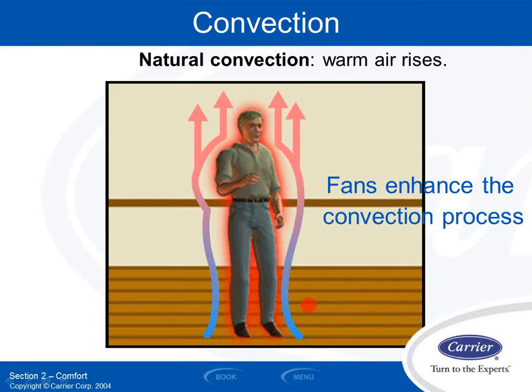all based on my body being the heat source. It's very similar for you guys that have been in apartment buildings or houses that have baseboard electric heat or baseboard hydronic heat sources. There are no fans in those baseboard heaters. Basically, the coil just gets heated up by the electric or water you're providing to it. When it heats up, that air rises out of the baseboard and new air comes in at the bottom. By the way, that's the same reason you don't stick boxes in front of the baseboard. It doesn't heat very well if you block the cool air from coming into the bottom of it.